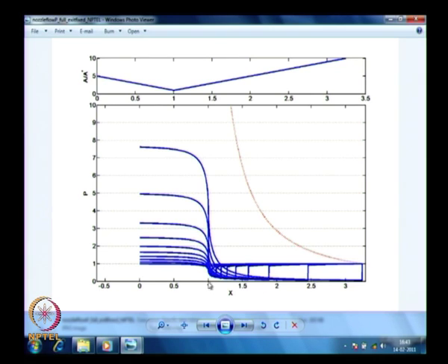If you look at this x equal to 1 location, which is our throat location, the pressure is continuously increasing after it gets choked. It is continuous, in fact even for some time it will be decreasing and then it will keep on increasing above that. At this point this is the pressure P star. If you look at that number, from there it will be roughly half. 0.75, half of that is 0.375, it is slightly more than that. So, this is my x equal to 1 point, P star is higher, it is above atmosphere here.